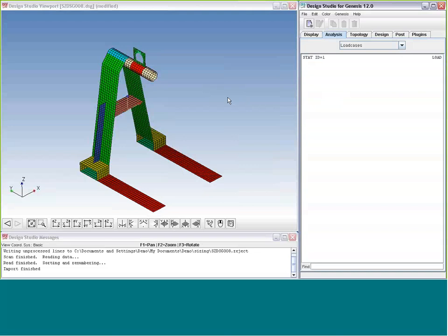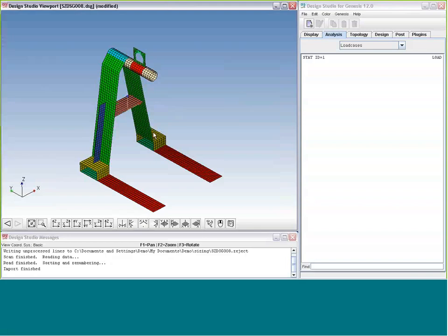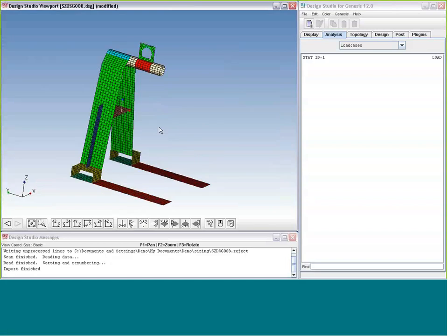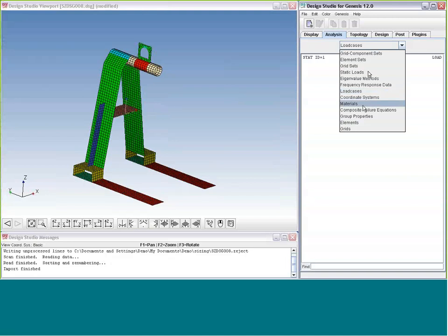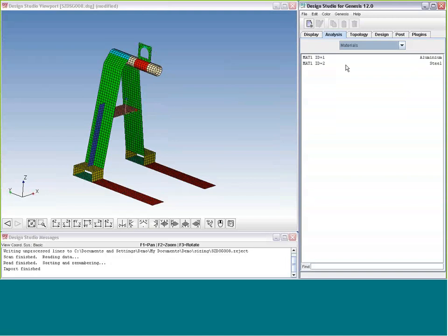Normally in structural design, we can say that the cost to produce the part is proportional to the mass. That's a very common assumption. And so if we minimize the mass, it's the same as minimizing the cost. This particular part has two different materials, an aluminum material and a steel material. And we actually only want to design the shells associated to the aluminum material.